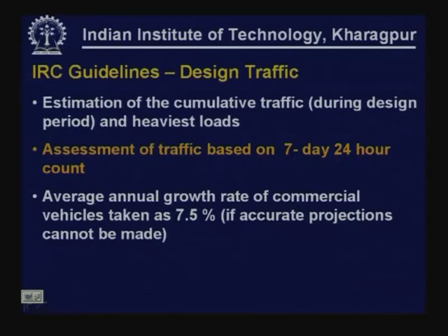Assessment of traffic usually has to be based on a 7-day 24-hour count. Obviously, we have to make traffic projections for the next 25 or 30 years of the design period, but this has to be based on the traffic counts that we make in the present situation for a short time period. So, this has to be done for a 7-day continuous 24-hour period.